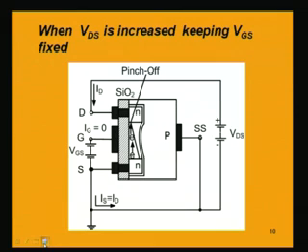Now, what will happen? When you increase the drain to source voltage, the width of the channel will be changing, because at any point in the channel, if we want to find out the voltage between the gate and that point, then we see that this voltage is varying. If we are here at the source, the voltage from the gate will be VGS, the gate to source voltage at this point.